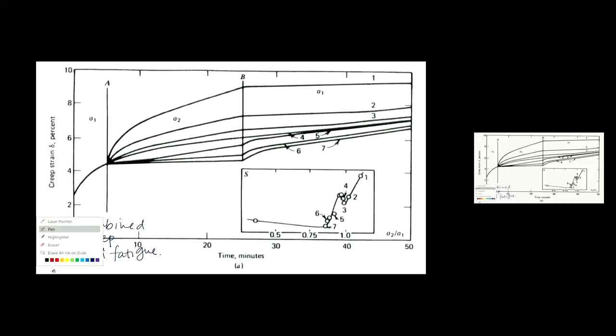If you know anything about lead, you know that it's a softer element, and even when you add it into other alloys, it's still not going to be a super, super hard material. So we would expect that this is a good material to study because it may have very high creep strains. Like you can see here, 0.1, right? So that's 10%. In the last example problem, it only went up to 0.01, right? So high potential creep strains here.